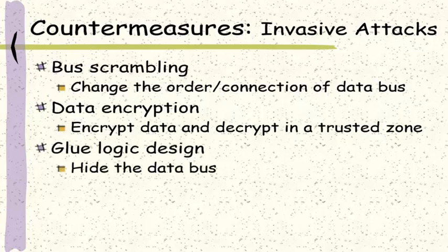Another way to defend against invasive attacks is the new glue logic design approach. In this design style, standard building blocks such as register files, instruction decoders, arithmetic and logical units, and input-output circuits are glued together like an ASIC instead of individual components. This hides the data bus, so it becomes impossible for attackers to find the signal to attack.